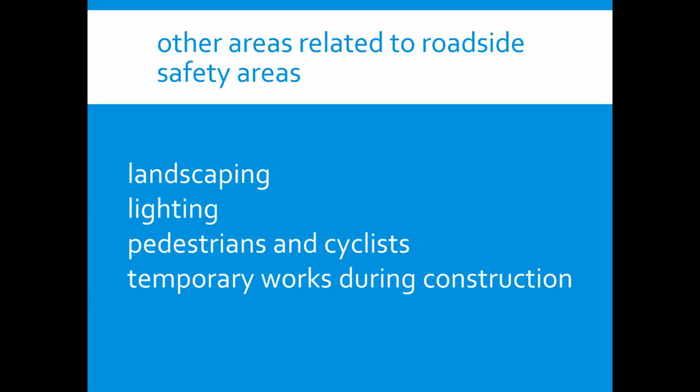Besides absolute lighting level, it is important to consider consistency and avoidance of dark patches. It will be a matter for each road agency to determine the extent of lighting provision on major urban roads. Where freeways intersect with the major urban roads, it should be common to provide for appropriate lighting of the intersections and access.